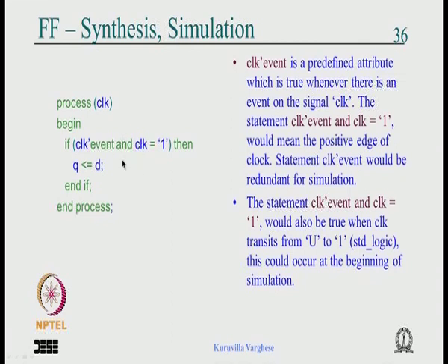You should think that the synthesis tool is just a set of algorithms, a software which tries to make sense of all the code you write. So you should stick to the standard rules of the game, not try to invent ingenious ways of describing the behavior and hoping that it will be accepted as that particular behavior.